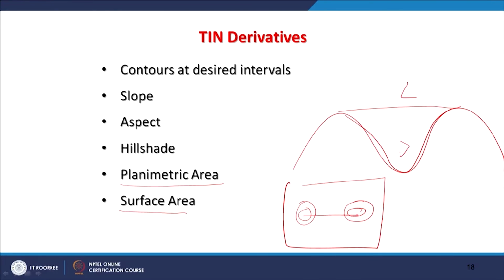So, whenever you are calculating area using a surface, either TIN or digital elevation model, please report the surface area, not planimetric area, because otherwise other estimations go wrong. Suppose now I am going for a road construction. In road construction you would say that it has this much length, but when construction starts, you have to follow the terrain something like this. So, it is a completely wrong estimation, and many civil engineering projects suffer because of these wrong estimations, either of area, volume or length. So, one has to be very careful while estimating or calculating length, area or volume.